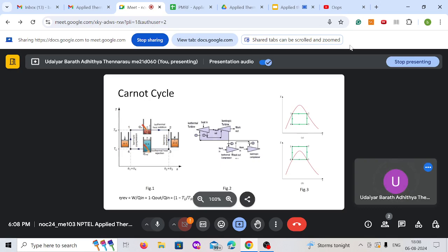And the other disadvantage, if you say, of the Carnot cycle is that it's independent of fluid. So whatever the fluid may be, you will get a maximum efficiency out of a Carnot cycle. But that also comes at a cost. So if you hypothetically can build a Carnot cycle, then the individual components, the processes 1 to 2 or 2 to 3, having a turbine or any component, its initial capital cost will be very high because you will require very big heat exchangers or compressors, as I told.